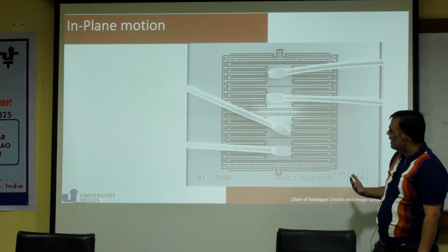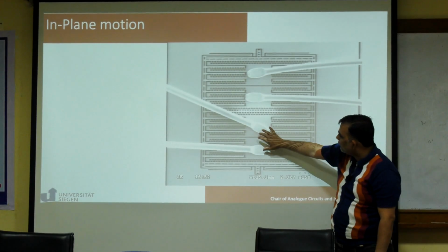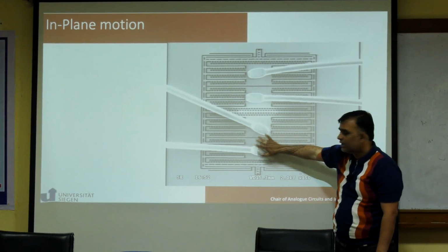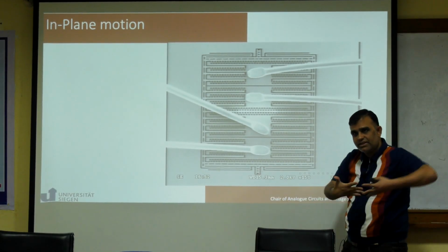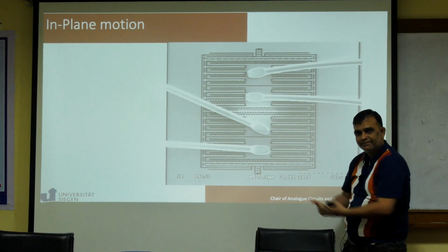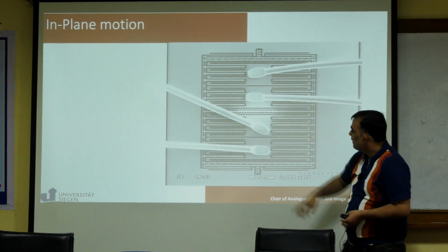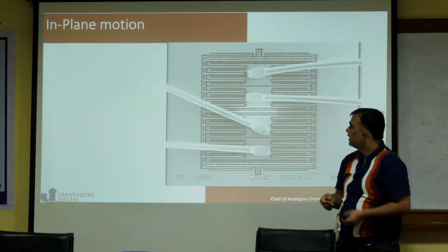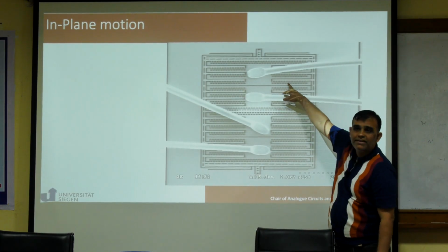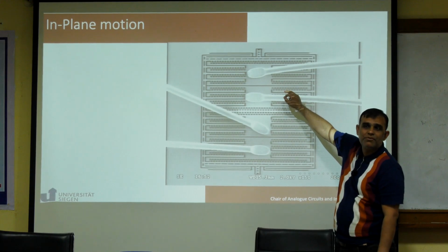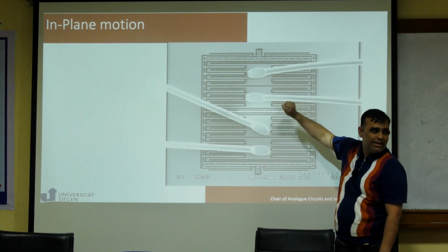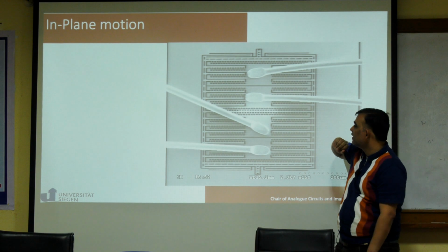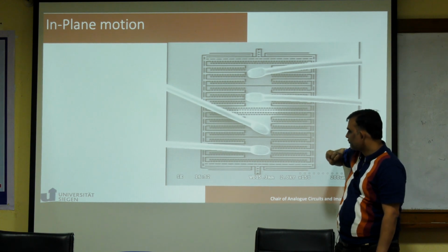The idea is as we apply electrostatic force from two of these, this whole structure starts moving. Okay? So I apply two of these to apply an electrostatic force, but then I use another two of these to measure by how much it is moving. Okay? And we'll see in a second how we measure this structure.